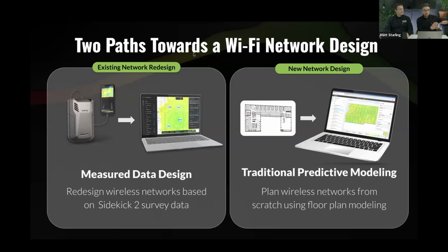Maybe you have an old network that's just 2.4 and 5 gigahertz only, and you want to simulate upgrading to a 6 gigahertz capable Wi-Fi 7 network. You can totally do that using Ekahau AI Pro Online. So what is it we use? Is it AI and machine learning? Yes, AI environment is the key. Okay. And Sidekick 2, of course. Okay, yes. So that saves you a ton of time, not having to draw any kind of walls or any kind of obstacles, things like that.